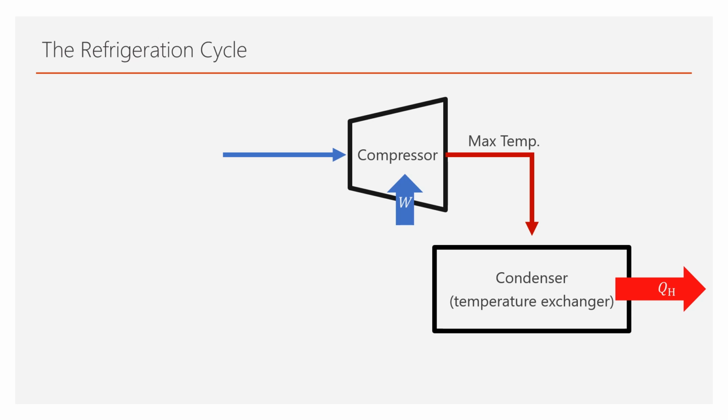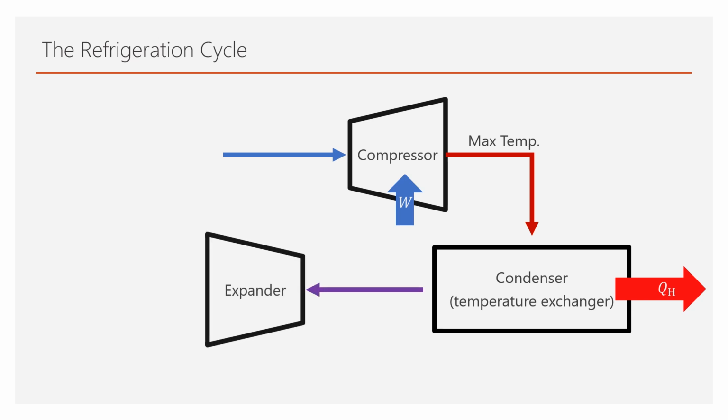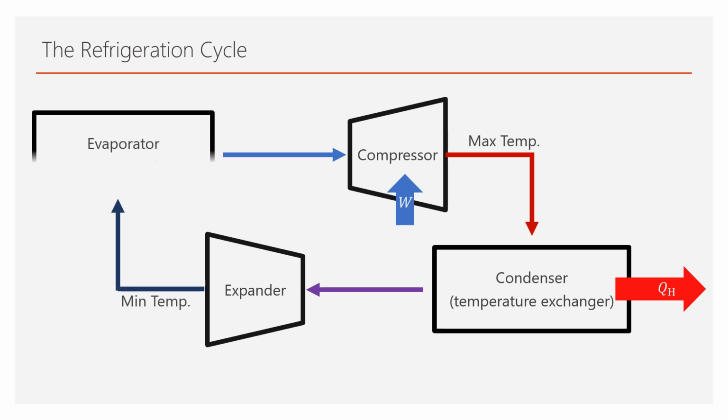The refrigerant is then allowed to expand through a device called an orifice tube. As the refrigerant expands, it passes through another heat exchanger that is inside a building or in the cabin of a vehicle, and that expanding gas pulls heat from the surrounding air, thereby cooling it, after which the refrigerant is returned to the compressor for an additional cycle.